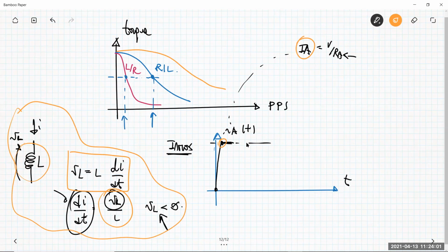Okay, so the technique, if you want to call it this way, is just to accelerate the turn off by applying the larger negative voltage across the phase. Okay, something that we will exploit tomorrow morning, starting 11:30.